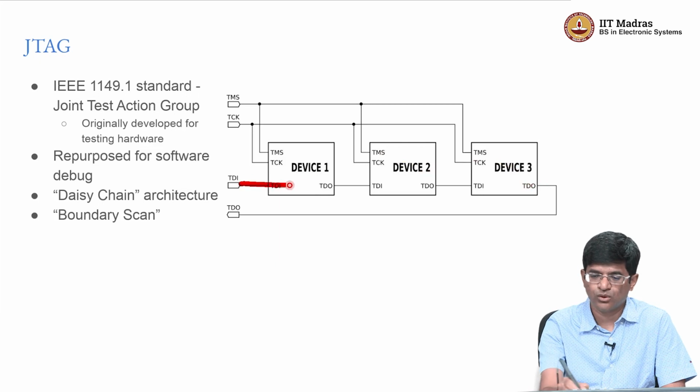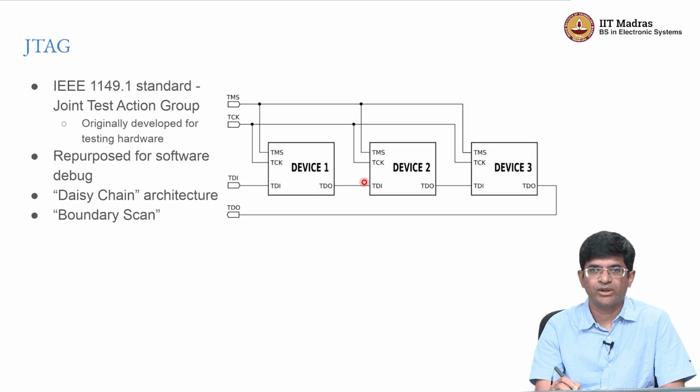What you would have is that you would directly talk to one module somewhere inside the CPU, whose job is to basically do at a slightly higher level things like single stepping or controlling the program counter or things of that sort, right? The moment you have some way of getting data into and out of a system in a controlled manner, it means that you can basically program it to do whatever you want, and that is what JTAG enables.